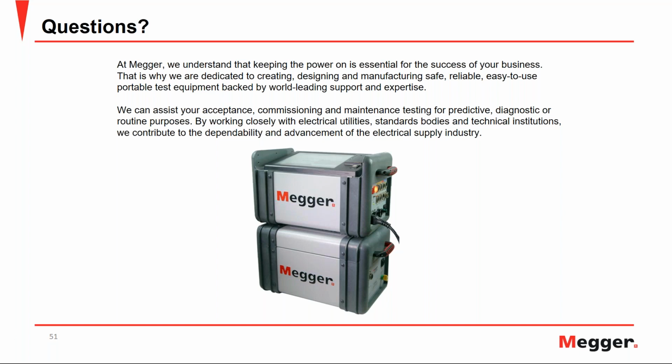When you perform, let's say, C high to low insulation, you are applying that voltage for no more than 30 seconds. So if you are putting rated voltage, if at all, to the transformer for 30 seconds, and that transformer is designed to see that rated voltage for 20-30 years, so certainly you are not stressing the transformer. It's not a destructive test.